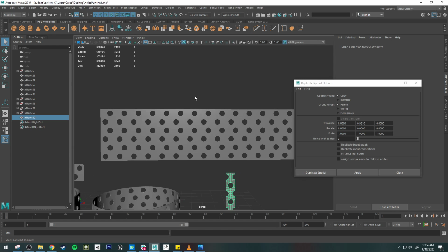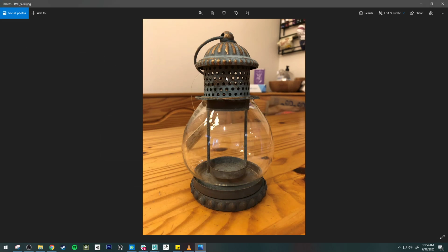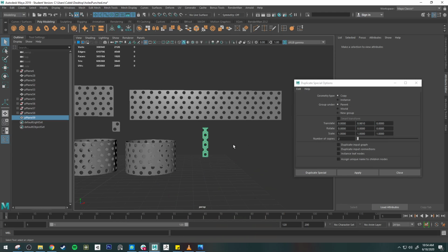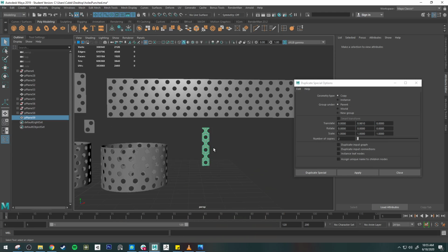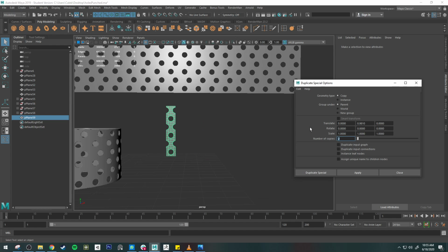This will, again, require taking a look at your mesh. So I can see this one is one. Let's see if these two right here is a single one. Or actually, I'll just count by these ones. So 1, 2, 3, 4, 5, 6. Right, so that's 1/4 of this cylinder. So I'd say about 24. The problem with this is... actually, no, we can just go for 24. So I already have one copy, so I need 23.